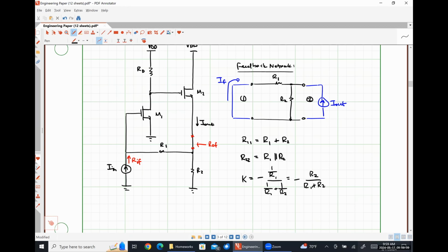So think about all of our feedback voltage amplifier relationships. Every time our feedback factor was positive, but our open loop gain was negative, so that it worked out for the negative feedback or everything to work out correctly. So this time, if we wind up getting a negative gain, we have positive feedback and instability. So just something to contextualize here.